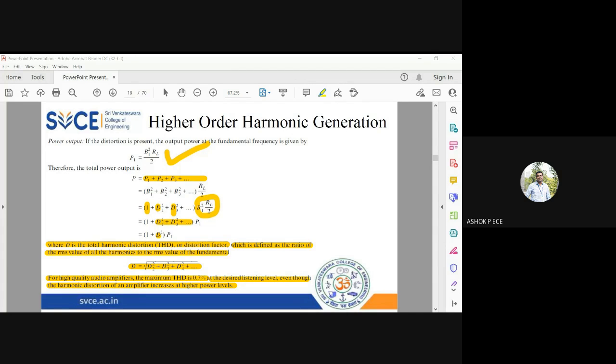Inherently the device has a heavy amount of noise, so you adjust the power level, you adjust the sound, you tune all the sound parameters in the mobile phone, and see that your headset is not giving that much clarity of the sound signal coming from your mobile phone. This means that some component in the headset is non-linear, so it is adding noise to your signal. That might be because of THD also.